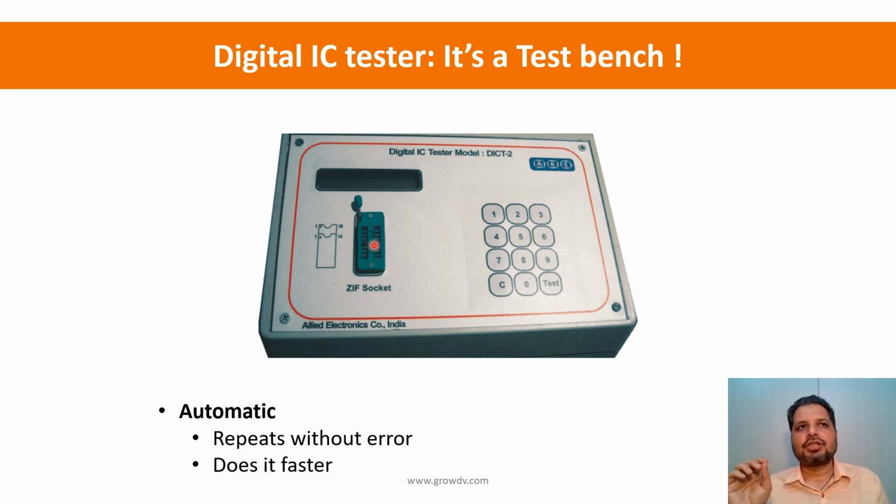So essentially two things, right? One is to generate all possible combinations of inputs and check the output. And second, being able to automatically repeat similar steps again and again, more efficiently, across all the tests. That's what we need. And that whole setup in the verification world is called a test bench, and those test benches are built using either Verilog, or currently the high level verification languages such as SystemVerilog.